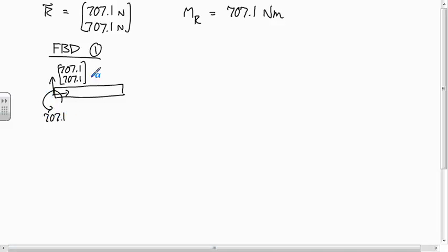What other loads are acting on this piece? Yeah, I'm not going to do it that way yet, but you're right. The way I'm going to do it is I'm just going to think of this as, so the stuff happening over here, we're not isolating that. So this force doesn't apply. But what does apply is there's a fixed joint between this member and this member. It's like these two are welded together, right? And so that means that there is an internal force vector, F, and there's a couple. I'll call this Fi for internal force, and I'll call this Mi for internal couple.